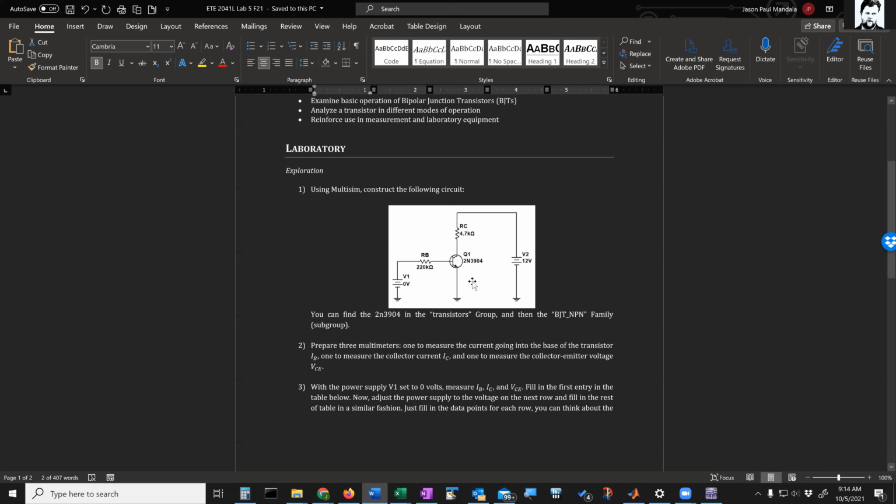And it can't go anything below 0 though, right? That's what we discussed last time. So the lowest the voltage drop across this transistor can ever go is down to 0 volts. The largest this voltage drop can be is all the way up to whatever your supply voltage is. So in this case, we have a 12 volt supply. So when the transistor is off, we should expect to see 12 volts across the transistor and 0 volts across